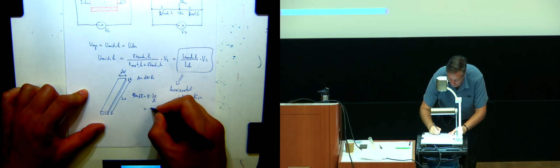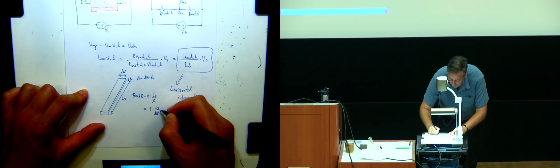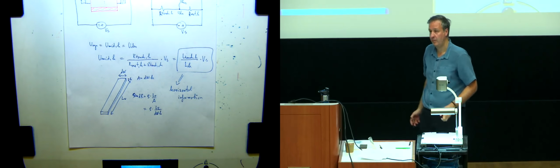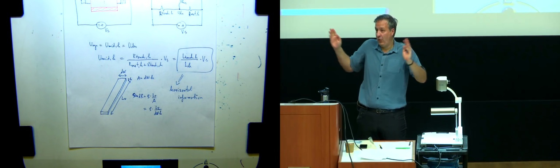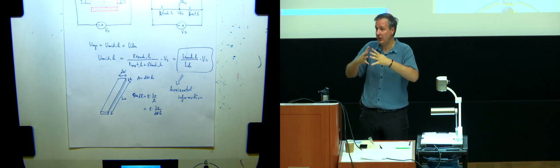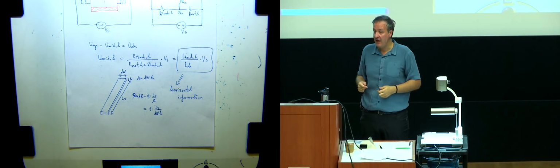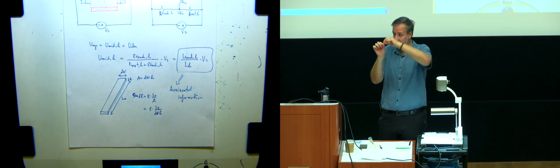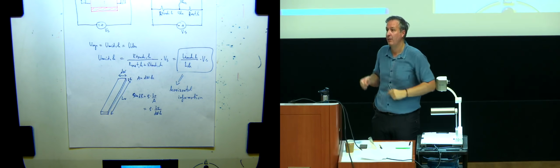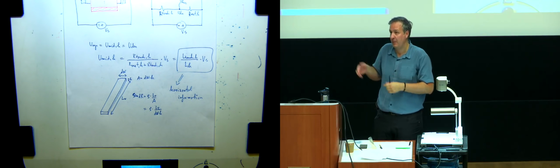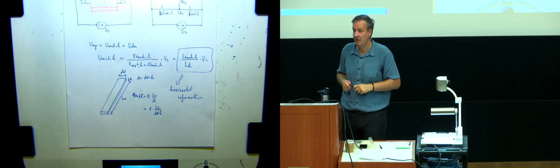And that would be rho times L_V over d_W times H. Make sense? And I can do that for millions of them. I get an approximation of the whole sheet. But because I'm now treating each strip as a separate one, I need to add some resistors in between, right? That gives me a model of how each strip talks to each other.